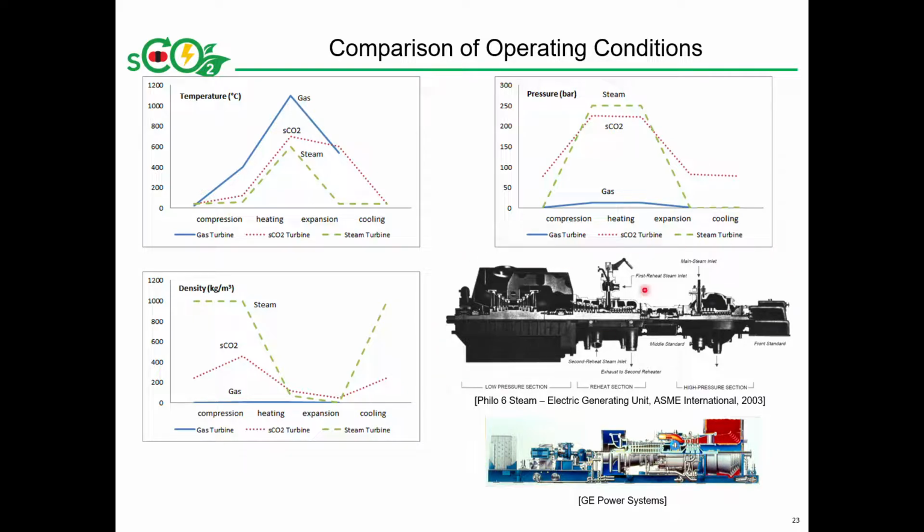Not shown on this slide, we also have a comparison with an sCO2 Brayton cycle that was nominally 100 megawatts and operating at a turbine inlet temperature of approximately 700 or 750 degrees C, that was partially designed at Carleton University by various fourth-year project students.